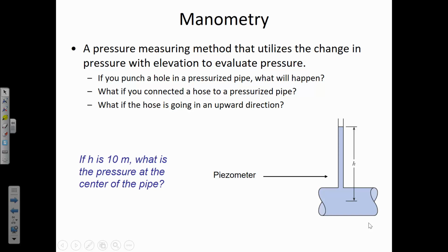But this piezometer is very similar to the way that water behaves in soil. There's something called the capillary effect, where when you have a really small diameter tube, the water level rises inside of that tube. And we'll have an illustration of that in the lab later this semester. So piezometers end up being interesting and important for a lot of different applications, but not for the measurement of water pressures in a drinking water network, because the pressures are usually so high.